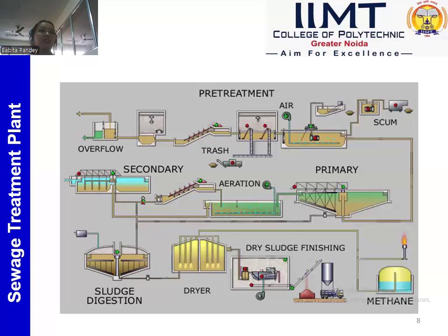So now coming to the last process, we go to the secondary sedimentation tank, or we can say secondary clarifier. What will happen in that? Now all the organic matter has already been decomposed in the tank by the biological treatment. What will happen now? All the microorganisms need to be dead now because they are in very large amounts. So we will stop the supply of oxygen. Without oxygen, all the organisms will die. They won't have the capacity without oxygen, so they will die. And we will be left with only sludge having chemical components in it.